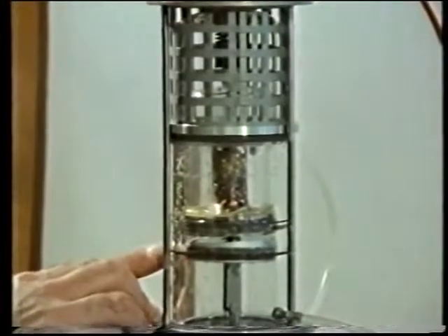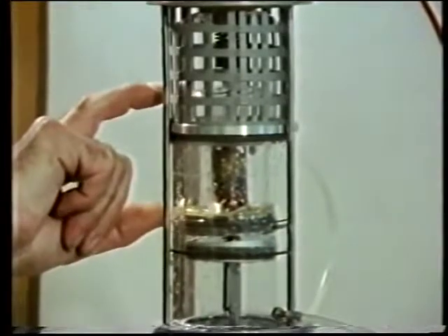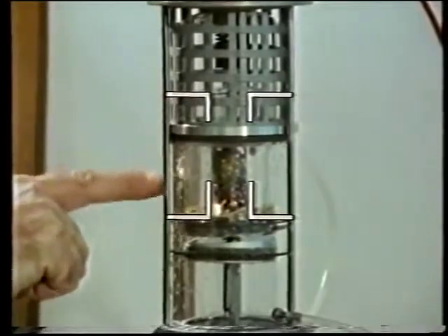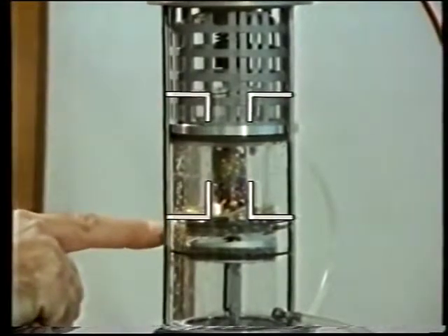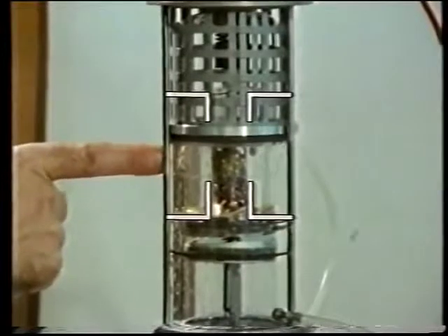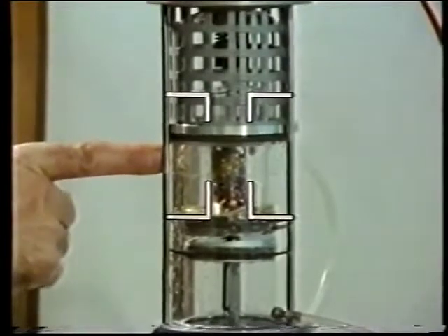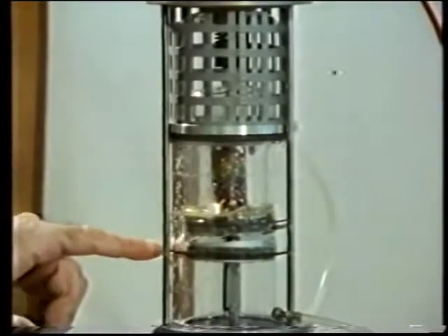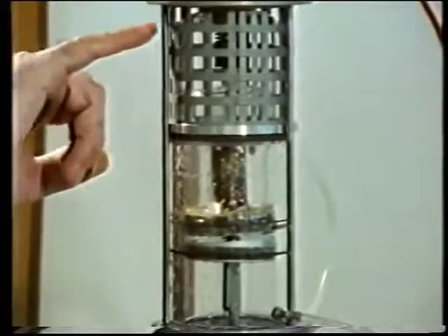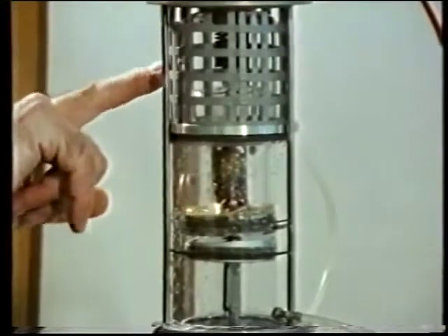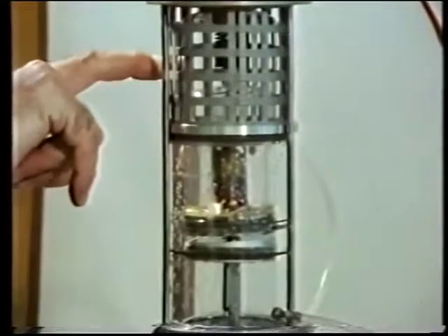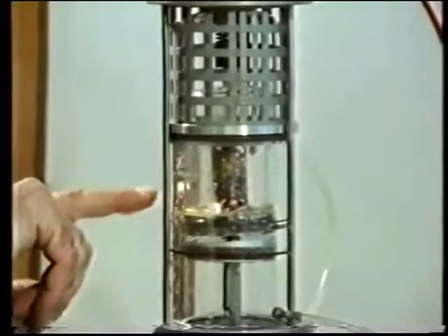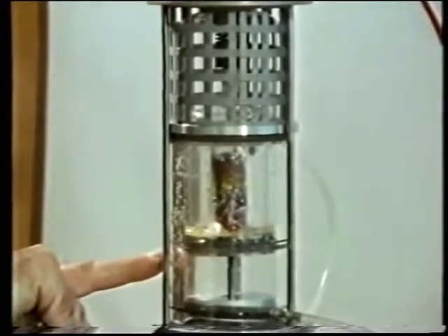The engine has a power piston and a displacer. In this case, the displacer is made of glass and has a passageway which connects the hot space to the cold side of the engine. The passageway has porous copper which acts as a heat store, which is called a regenerator. With the power piston and the displacer in their top position, the gas is contained wholly within the hot space. The gas is at high temperature and high pressure. High pressure gas forces the piston downwards, which produces a power stroke.